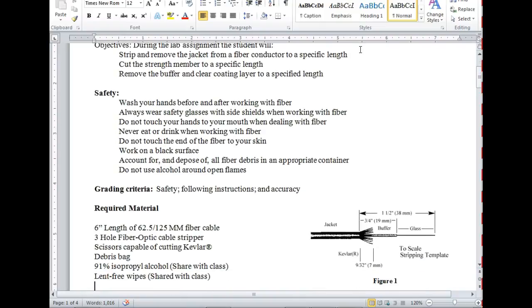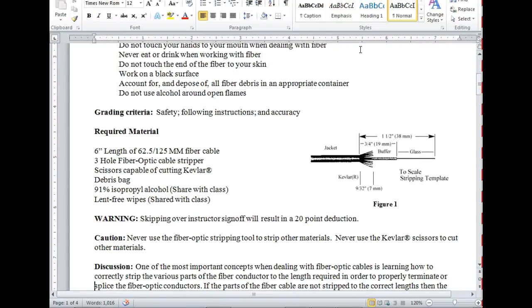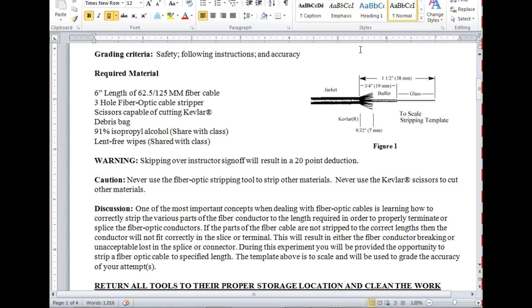And then what we'll do next is I'll show you how we can actually cut the fiber. We don't ever cut the glass fiber. I'm sorry, we can cut it with anything. But the problem is if you cut it with a regular pair of cutters, you don't get that perpendicular surface. It'll be fractured. It'll be at an angle and stuff like that.